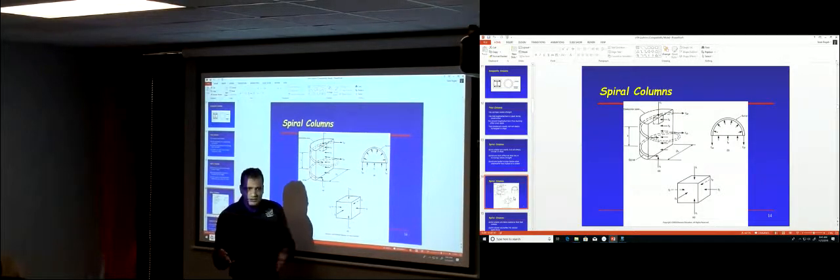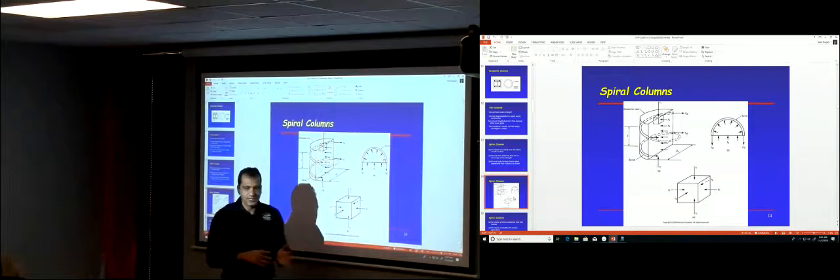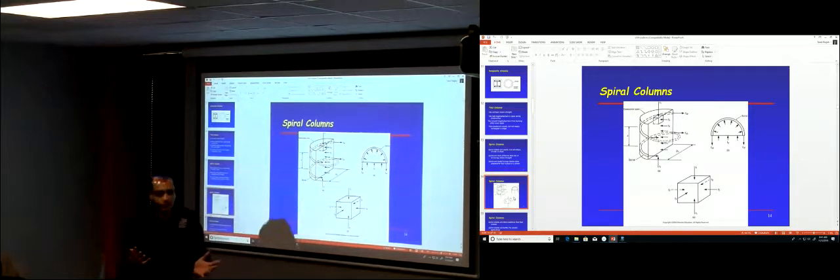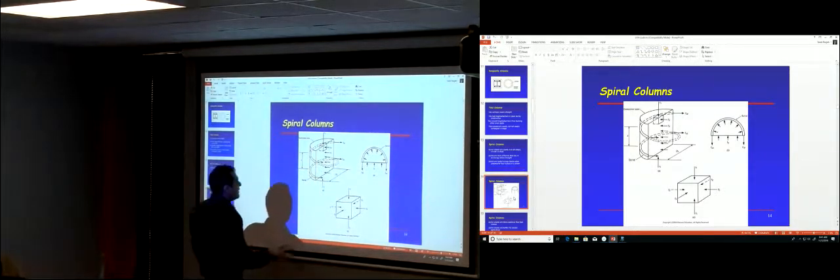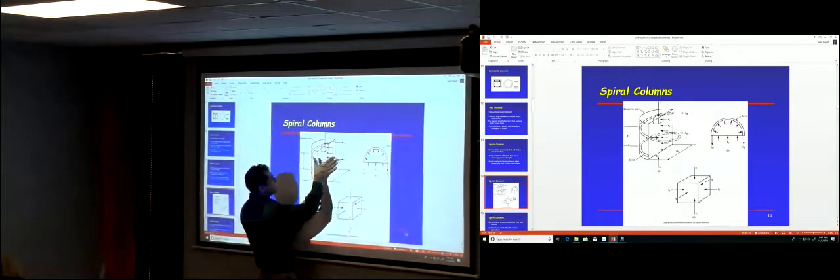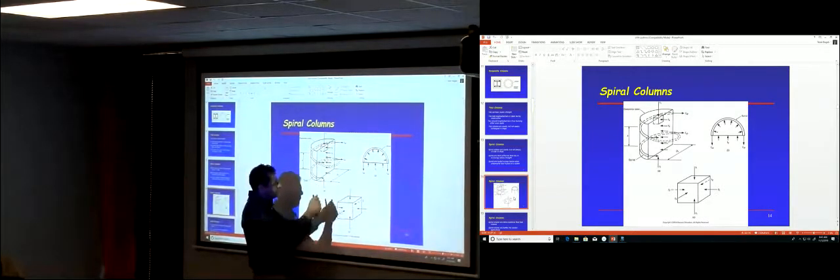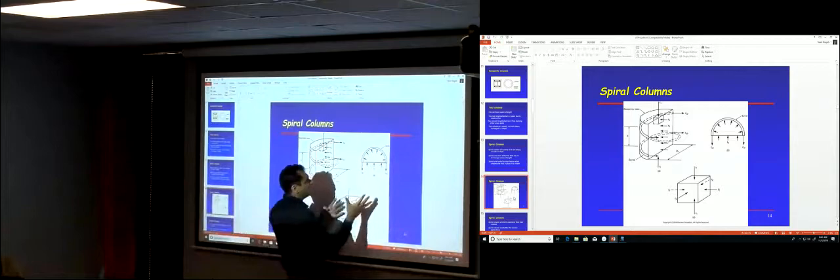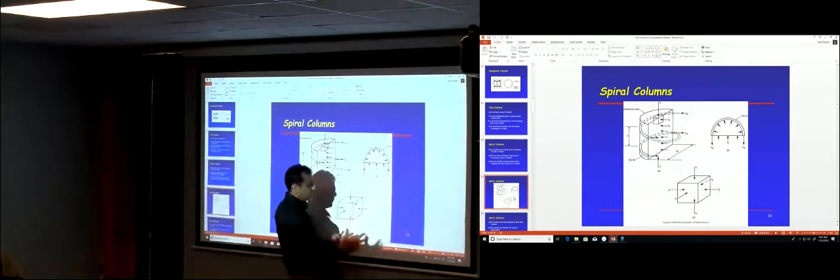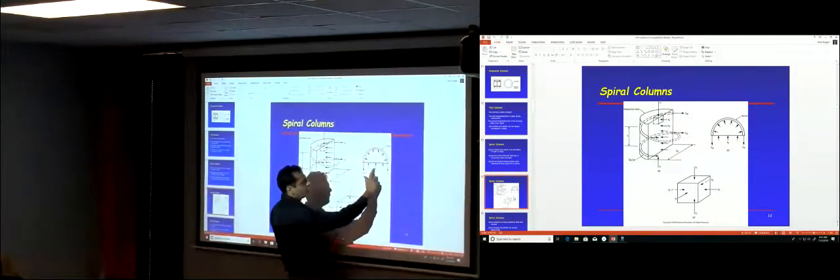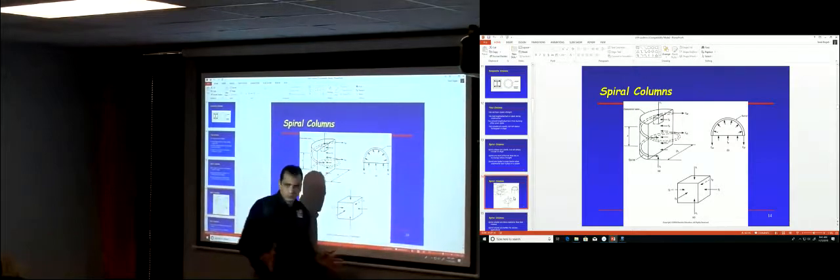Yeah, equal to the yield stress, then that's the failure point. The stress in those bars cannot be larger than the yield stress. And now, the confinement in the stirrup will put horizontal stress on the core of the concrete. We're going to name this F2, okay?